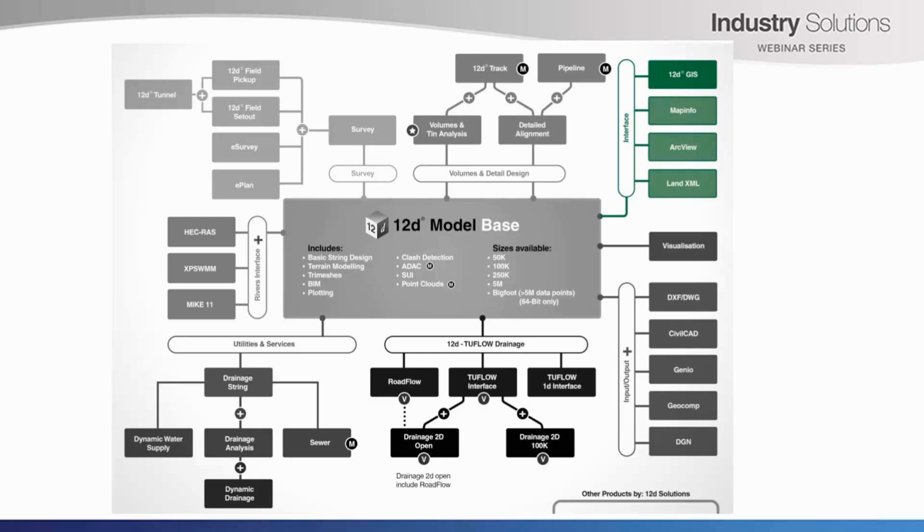The 12D model GIS. This module provides an interface between 12D model and other spatial information systems such as GIS and web mapping utilities through the use of open source FDO, which is feature data object technology. We can link up with ArcSDE, ArcGIS and ArcGIS Server, MySQL, OGR, Oracle, SQL, Web Mapping Service, Web Feature Service, and the data from within 12D model can be directly added to the connected spatial information server or database, removing the need for output files to be created to share some data.